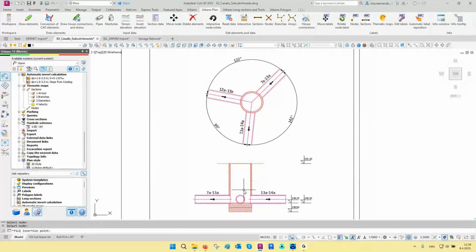First rule, which is most important: the main array, so the pipes that have the same array name, will always be shown in the longitudinal section, and other pipes will always be shown in the cross section. But even if you have all the sections with different array names, of course, the best way would be to just connect the main array sections.